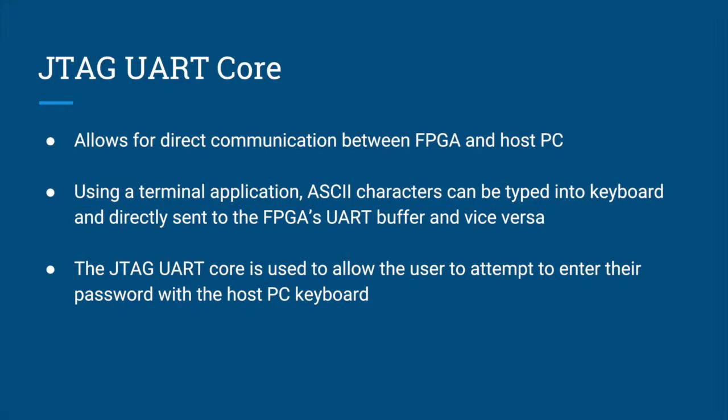The JTAG UART core is of primary importance for the control FPGA. It allows for direct communication between the FPGA and a host PC. Using a terminal application, ASCII characters can be typed into a keyboard and directly sent to the FPGA's UART buffer and vice versa. The JTAG UART core is used to allow the user to attempt to enter their password with the host PC keyboard.